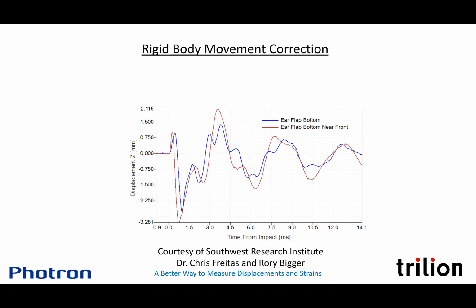Sometimes normal patterning works just fine. Sometimes, because it's going to look so different from the left to the right camera in the stereo pair, for really high porosity foams that have caves in them, the best approach is a single camera looking straight and adding some supplement to the pattern. We're not going to be able to use the porosity itself as a pattern. We are going to need to apply a pattern.